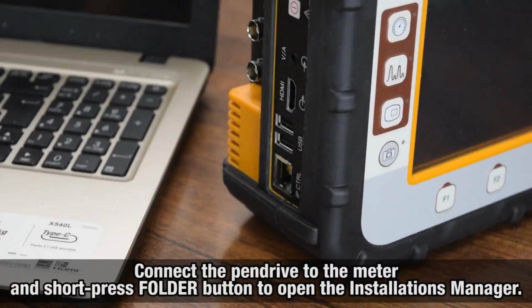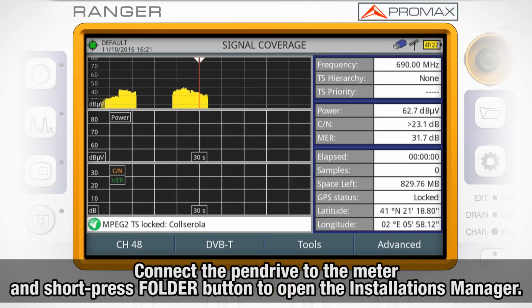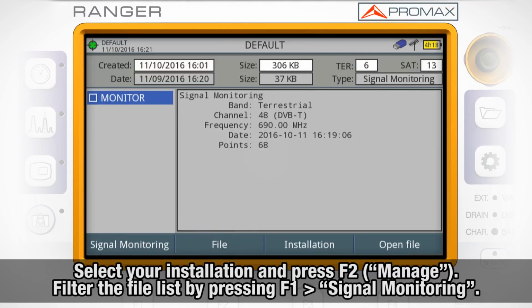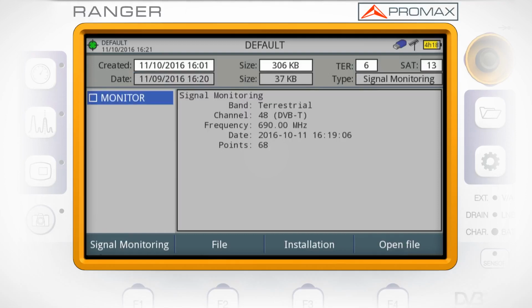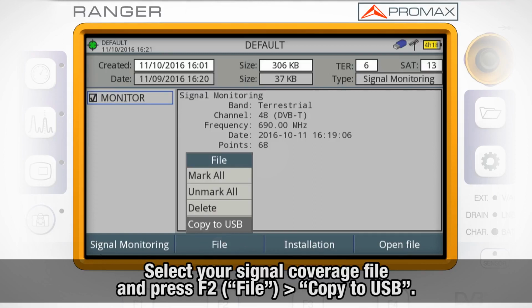First, we will need to connect the pen drive to the HD Ranger 2. We will access the Installations Manager by pressing the Folder button, select the installation where we are working, and press F2 Manage. Once in the Installation Manager, we can filter the list of files shown by pressing F1, All, and choosing only Signal Monitoring Files. We select our signal coverage file and press F2, File, and Copy to USB.